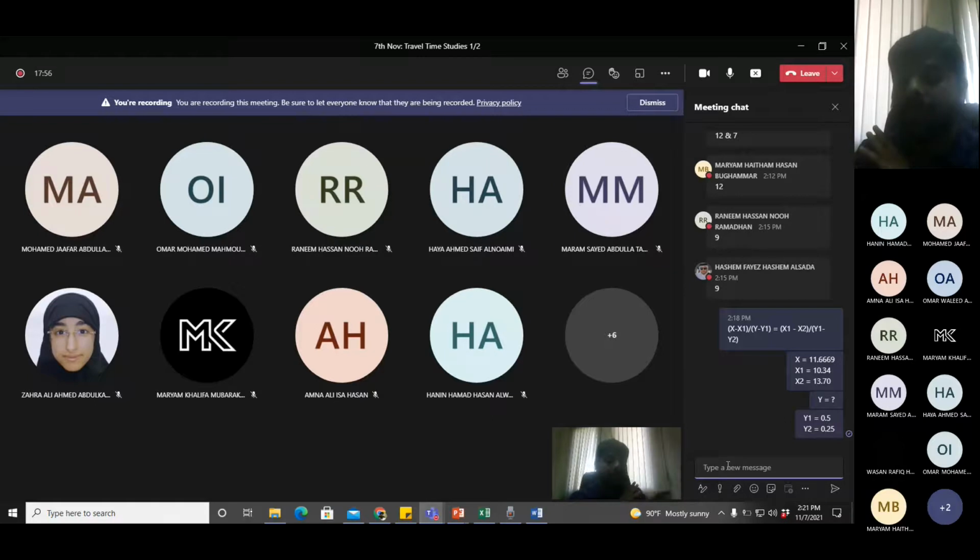If you remember, this was the main objective of doing the chi-square test: to mathematically prove that spot speed data follows normal distribution. We discussed another approach before, which was looking at the shape of the frequency distribution curve. If the curve is bell shaped, it is normal distribution, otherwise not. That was a graphical approach. In cases where the graphical approach is not valid, you cannot apply it, and you can apply the chi-square test to know if the data follows normal distribution.